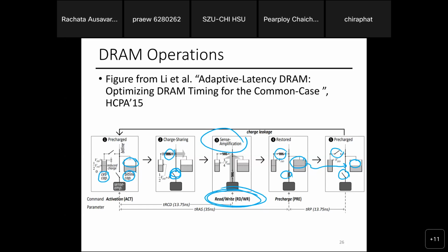Okay, got it. So in the case of the write, you don't amplify the signal inside DRAM. You amplify by draining and rewriting the signal that comes from the external source, which is the data you want to write. We use the external constant voltage. Yes, that's the data pins that go inside the DRAM.